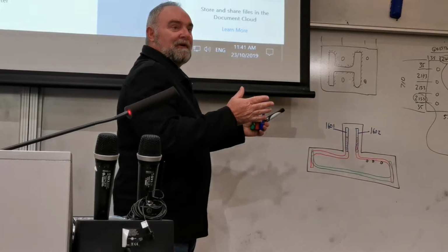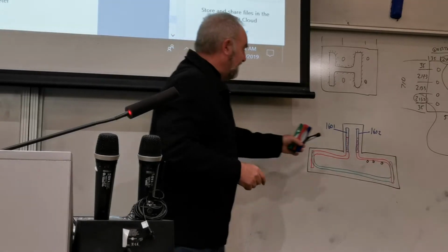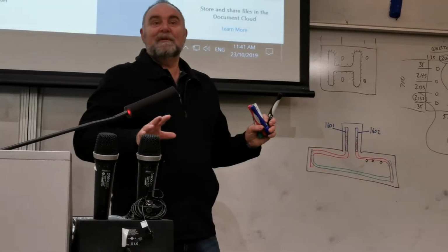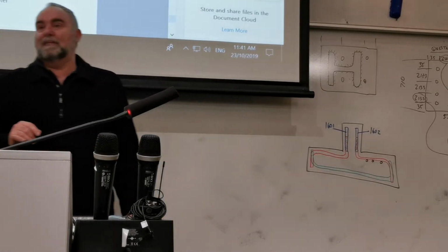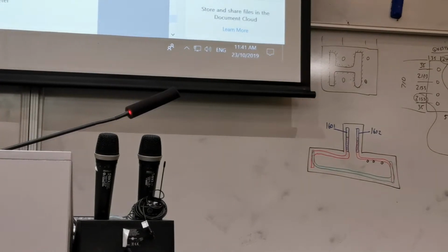So all you need to do is calculate the number of one of those, like say 1601, and because they all lap with each other, the number will be the same for all of them except for the black bars. So if you get asked a couple of the number offs in that reinforcing sheet, assuming you calculate one of them correctly, it's easy marks. Okay?